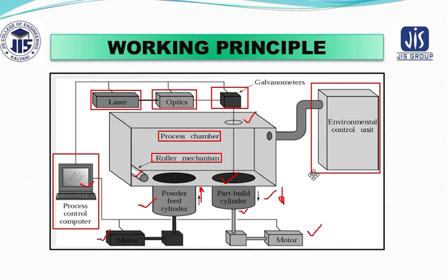So my answer will be wax, metal, ceramics. All these are basically appropriate binders, and the material that you are using includes polymers like ABS, PVC, nylon, polyester, polystyrene, epoxy. With the help of wax, metals and ceramics, which are to be considered as appropriate binders, it is most common to use polymers, because of the smaller, less expensive, less complicated laser required for sintering.